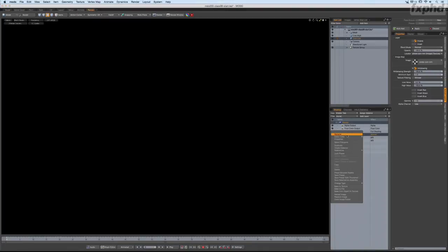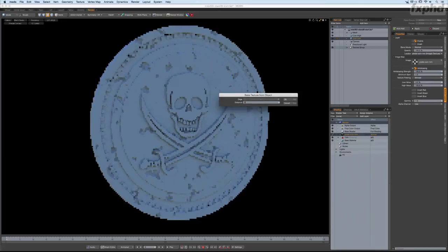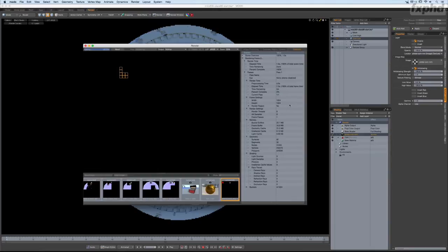This is one of those areas that you'll just have to fine-tune a little bit as you go through this process. Let's do 50 millimeters. We'll hit OK. And now let's see what the computer is going to capture inside of our normal map. Yeah, check it out. Now we're getting much more detail. We're starting to get all of the rings from the high-resolution object showing up inside of the normal map. And overall, this is looking very, very good.